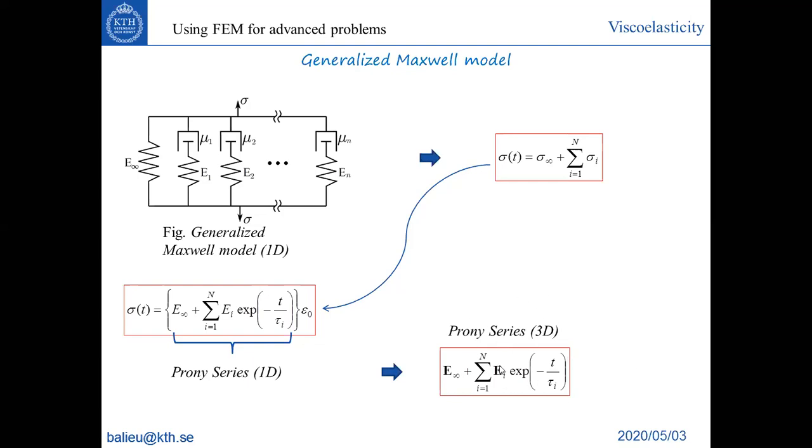This was the stiffness tensor, the tangent matrix that we discussed last week, that you use to calculate your element matrix, and assemble in your global stiffness matrix that you need to solve your finite element solution.